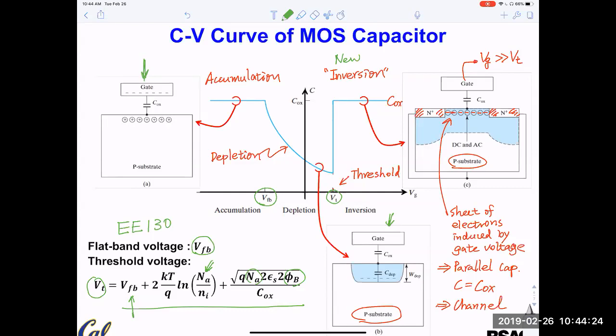This really means we precisely control the dopant, the doping depth, doping type, and uniformity across a 12-inch wafer when you do the processing. When you put down the gate oxide, it's uniform to within basically one atomic layer across that 12-inch wafer. This is the level of control that enables us to enjoy all these nice features you are using on your phones. This is a very powerful IC, with lots and lots of these devices in there.